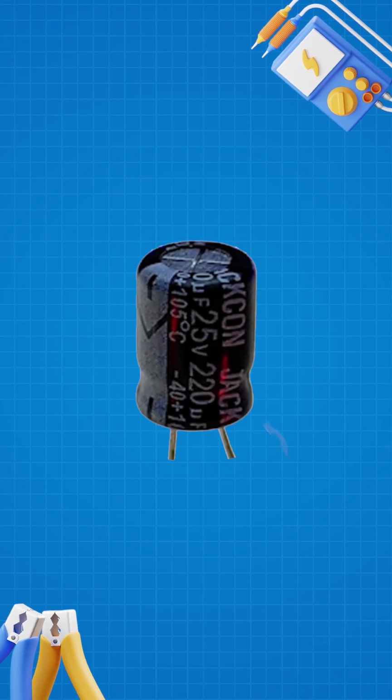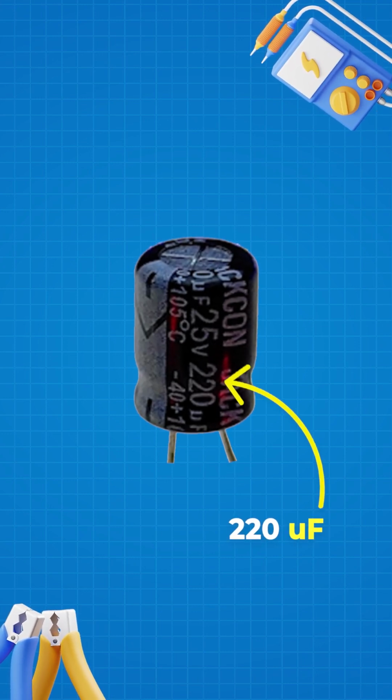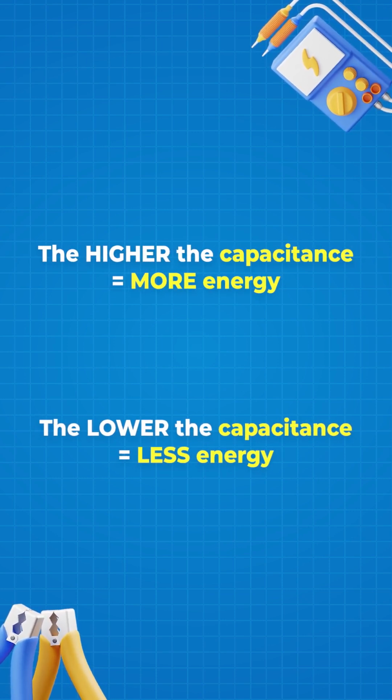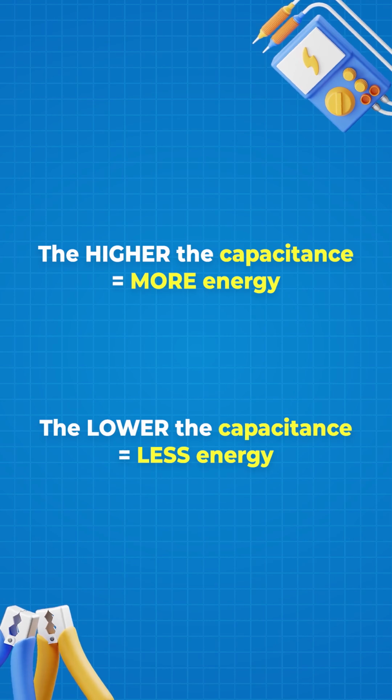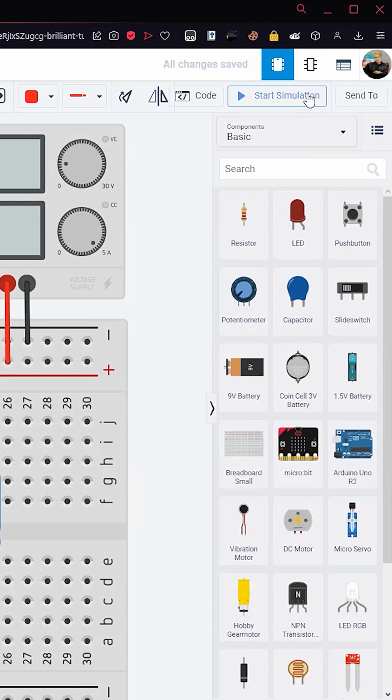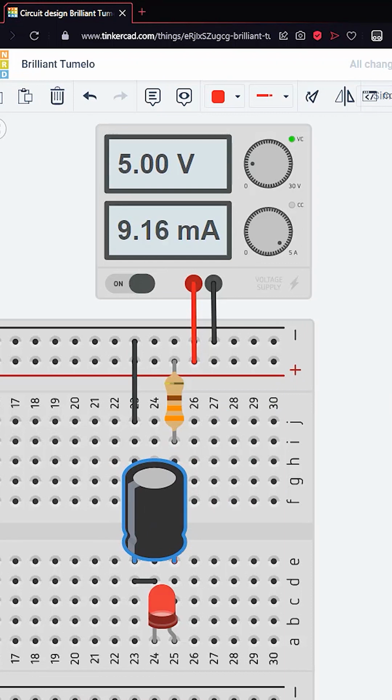For the farad value, it depends on the time you want it to take to fade out. Meaning, the higher the farad value means longer time, and the lower the farad value means shorter time. If you have no electronics components yet, you can visit Tinkercad.com and try to experiment with the capacitor there.